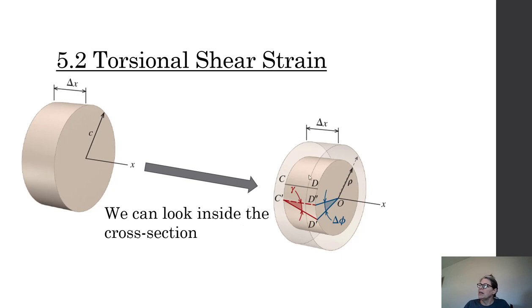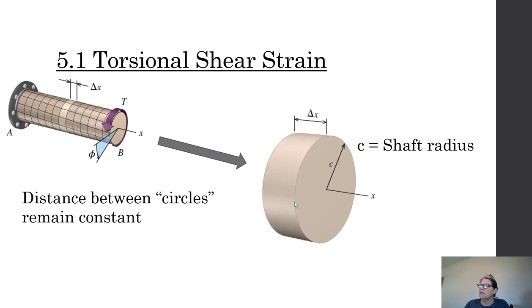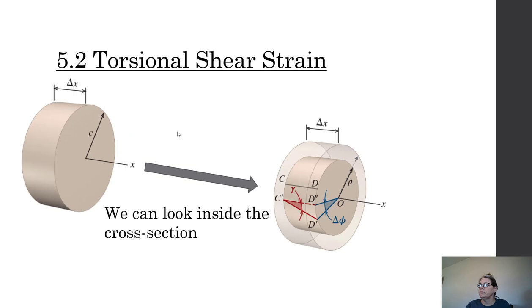So we're going to be looking at that shear strain. Remember, that comes back from, let's go back here, that's back here from the shear strain. If we drew where this line was originally, it would be straight. And we can see that it's twisted from it. That's going to be our shear strain. We can literally see that box goes kind of cockeyed. And then phi is going to be the change on our radial line.